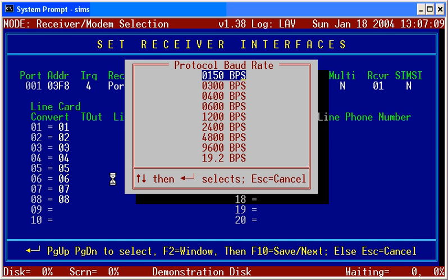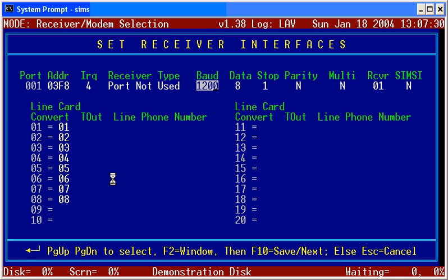There are a couple of receivers that are set to certain baud rates. For example, the Osborne-Hoffman 2000 is set for 9600, cannot be modified, and they have their reasons for that. That's okay, but we're saying if you have a selection, I would recommend you stay down in the 1200 baud range. There's no sense going lower, but there's really no use in going higher.